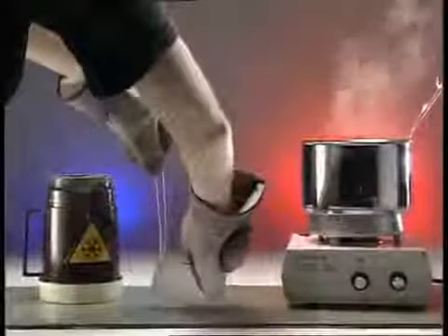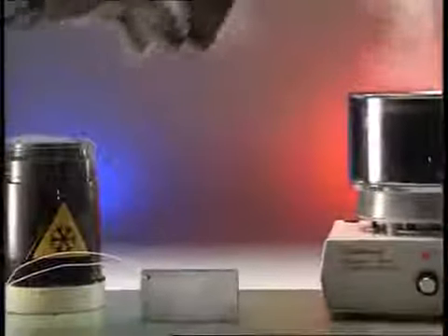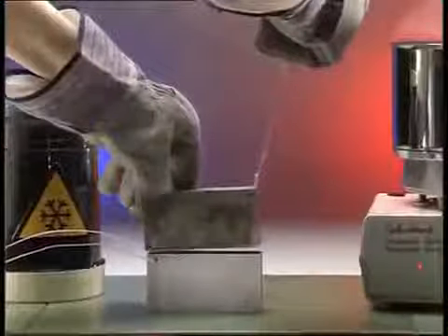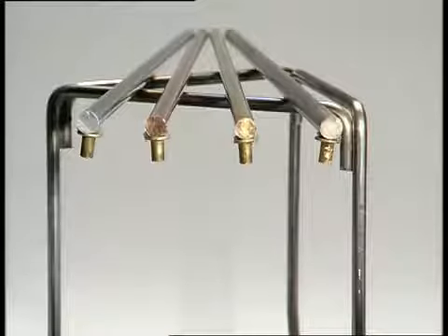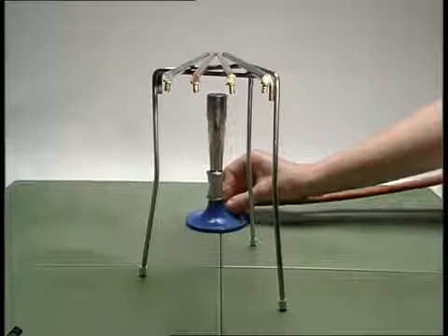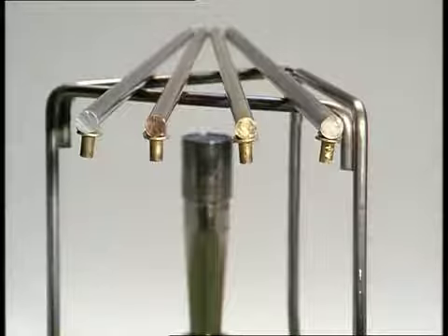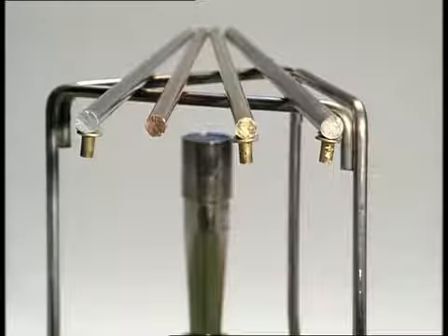Here's another example. Put a hot block of metal on top of a cold block and see what happens. Which of these metal rods is the best conductor? Aluminium, copper, brass or steel. On one end of each rod, a small rivet has been stuck with a blob of petroleum jelly. The other ends, furthest from camera, are all heated together with a Bunsen burner. The jelly on the copper rod melts first.